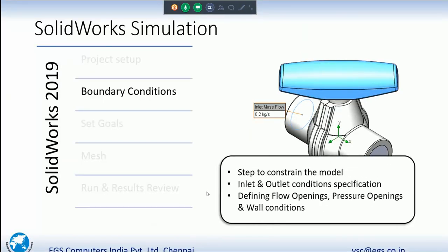So setting up what fluid is going to flow and at what rate, those conditions will be initially set up in the boundary condition parameters, and other conditions like what the initial pressure will be and what the outlet pressure will be, assuming it, or the initial development stage conditions, can be defined here.